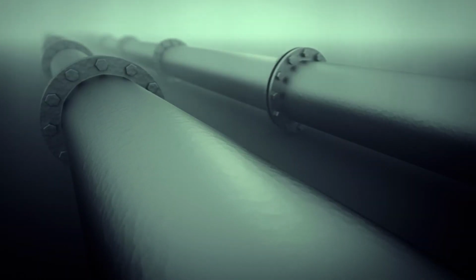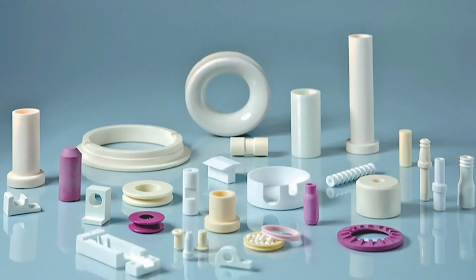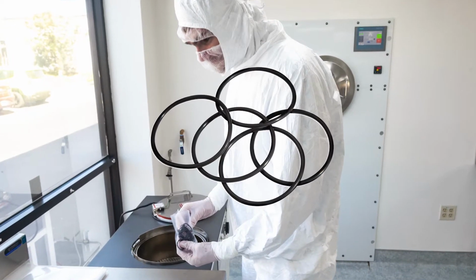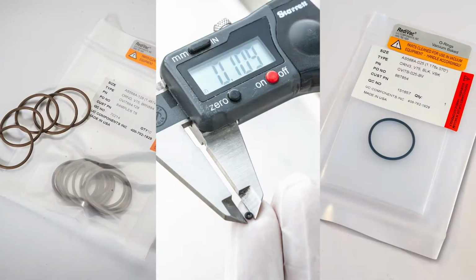However, the most common form of outgassing is water on surfaces, in the atmosphere, and trapped within porous ceramics and metals. O-rings also have vast amounts of trapped water, often amounting to over 2% of their total weight.